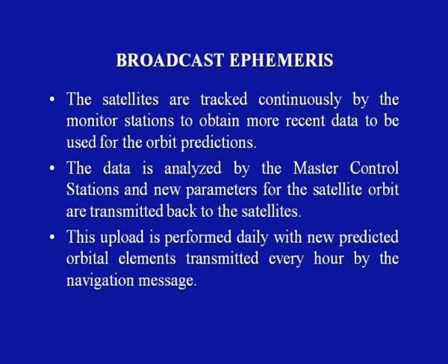The satellites are continuously tracked by the monitor stations to obtain more recent data to be used for the orbit predictions. The data is analyzed by the master control station and the new parameters of the satellite orbit are transmitted back to the satellites. This upload is performed daily, with new predicted orbital elements transmitted every hour by the navigation message.